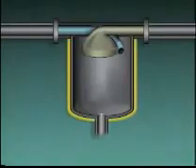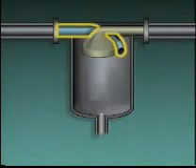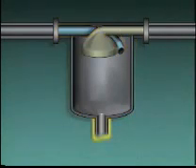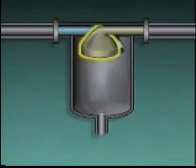The next auxiliary device we'll look at is a demister. Air and other gases generally contain some moisture vapor. When gases are compressed and then cooled, the vapor often condenses into liquid droplets that can damage some types of pneumatic equipment. To prevent this from happening, moisture separators or demisters are often used to remove these droplets. This illustration of a demister includes a shell, a gas inlet line, a liquid outlet line, and a gas collector, which is connected to a gas outlet line.